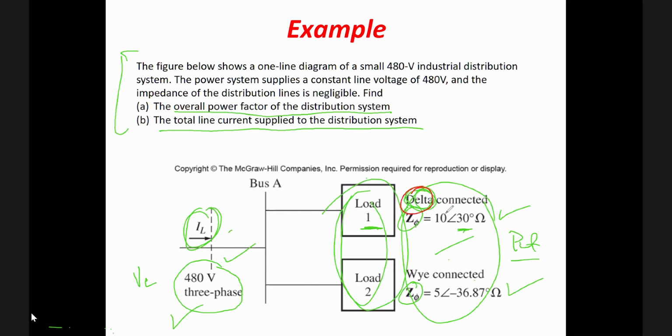Could you explain more behind the idea that if the voltage is not specified, I have to consider it as line or phase? Well, in written problems, meaning that you don't have the single phase representation or one line diagram, if I say, for example, that the voltage in the Y connected source is 120, without specifically mentioning whether this is line voltage or phase voltage, take it by default as a phase voltage.